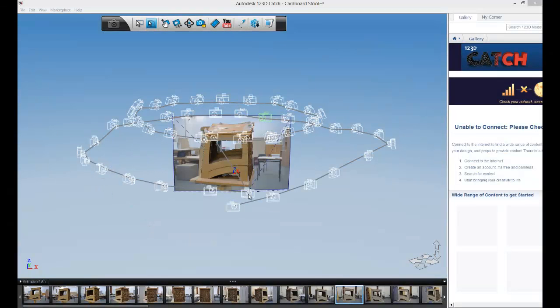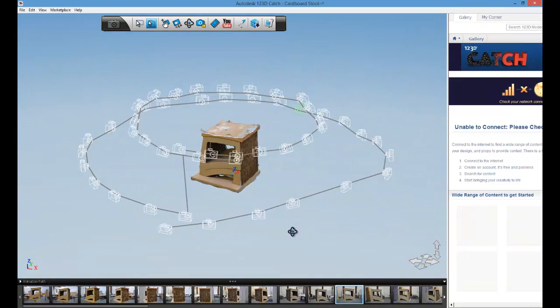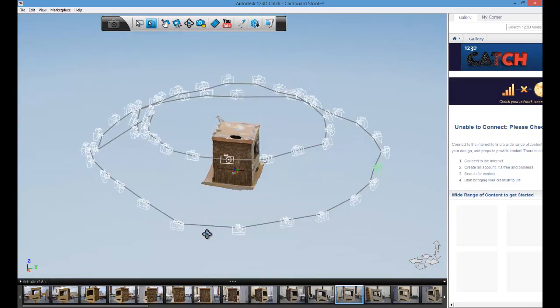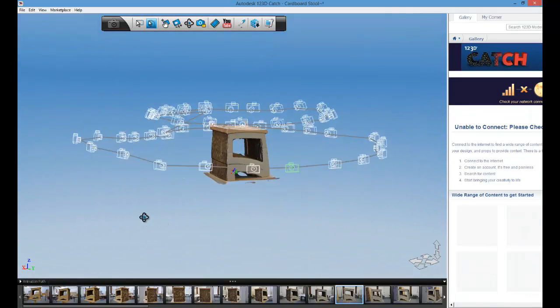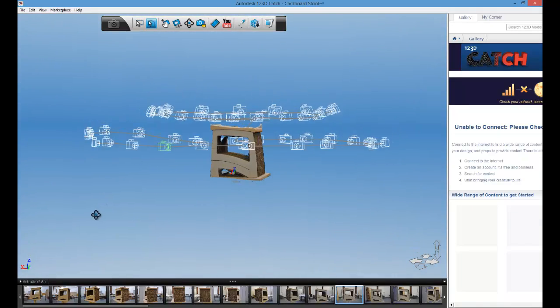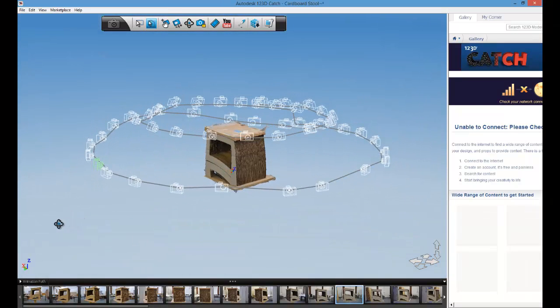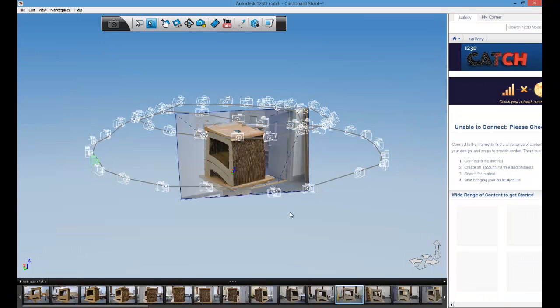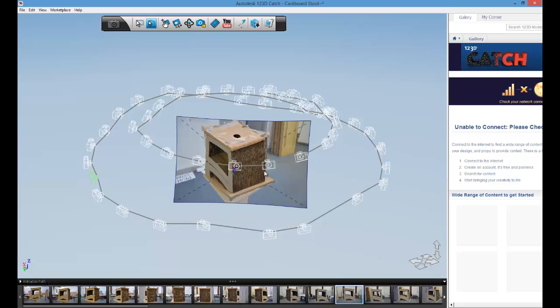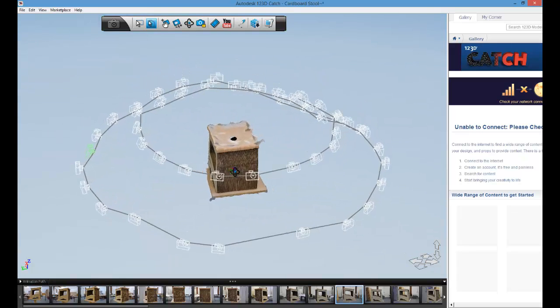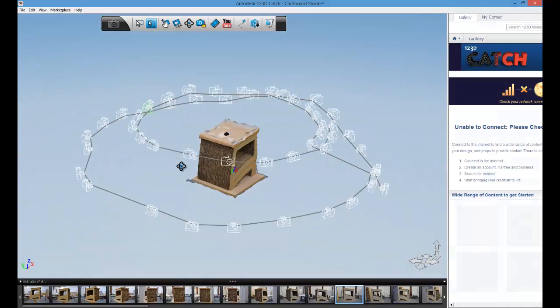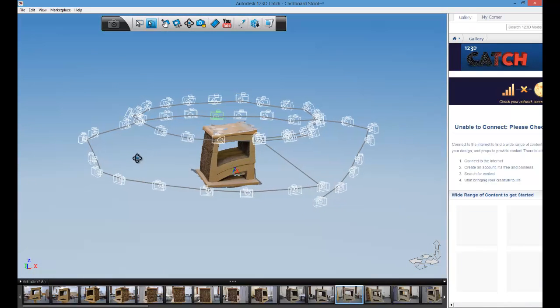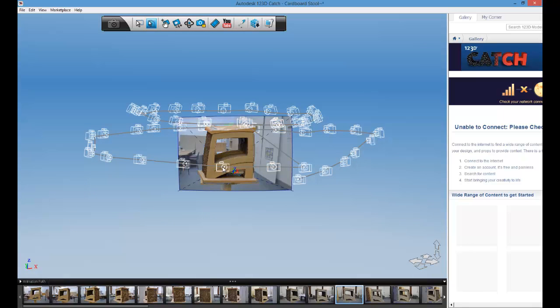When taking the photographs, it is important that they are taken in sequence around the object. It is recommended that 2 rings of photographs containing all of the object be taken, one at a low angle, capturing the elevations, and one at a higher angle, capturing more of the top of the piece. Once this is done, more detailed photographs can be taken of certain elements that may not have been captured by the full-length shots. Photographs should be taken at angles of about 20 degrees around the object. This is about 18 photographs in each loop around the object. However, this will vary depending on the size of the target object.